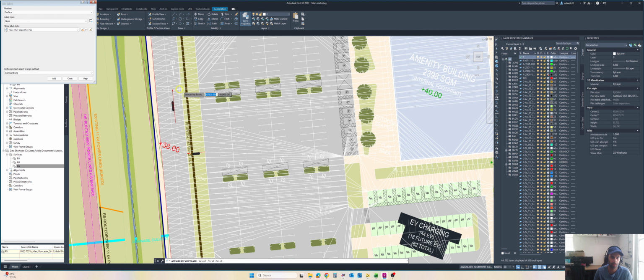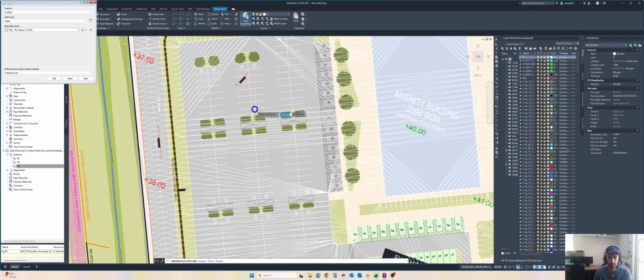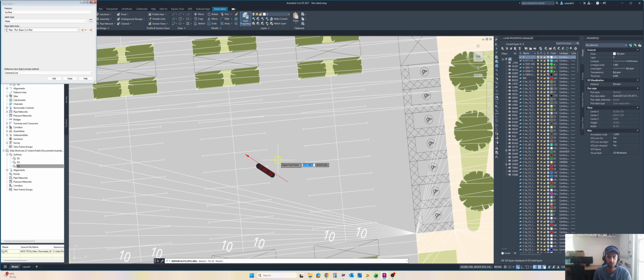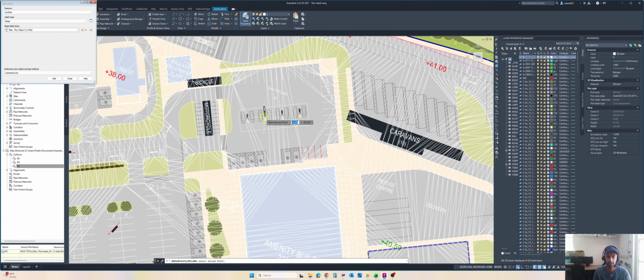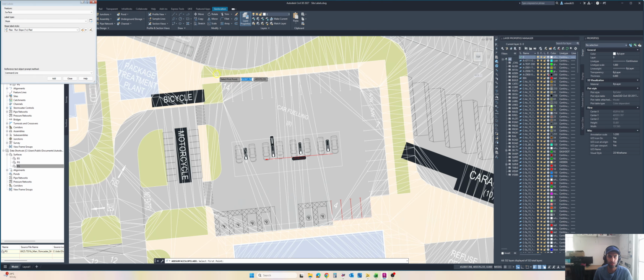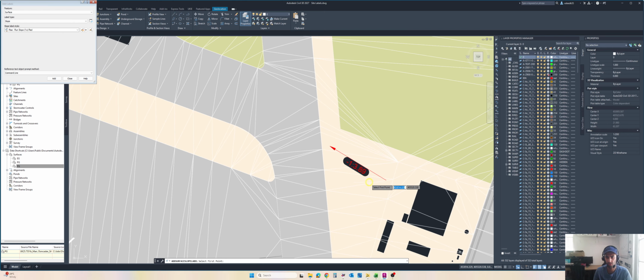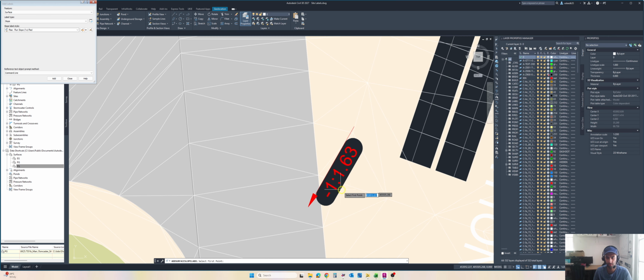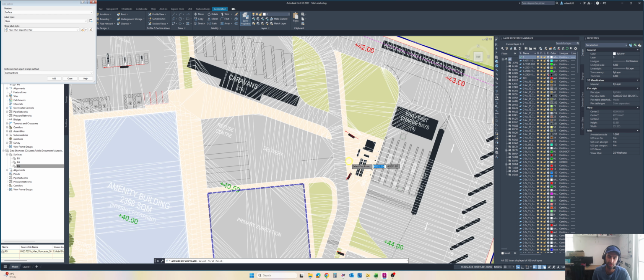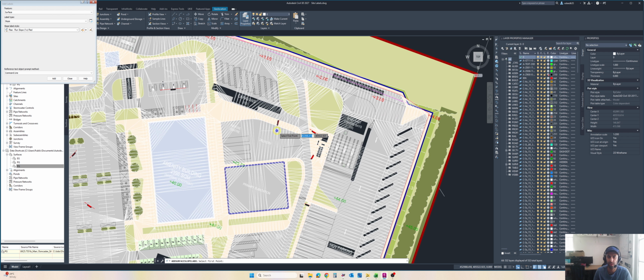And we can do it like this, and give some of their slopes. This way you can do the slopes for a site, for a better understanding of whether we need retaining walls or if it is fine. So 1 in 3.8, 1 in 1, so it's a bit slopey here. Maybe they need some kind of wall here. And these are the footpaths, so it's 1 in 53, that's fine. So 1 in 20, 1 in 30, 1 in 40, 1 in 50 is fine for the footpaths.